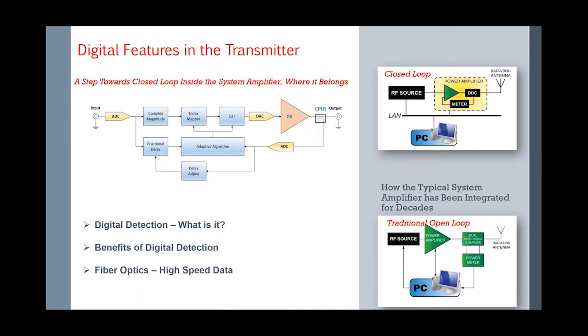The advantage of combining digital with RF is the capability to correct the errors existing in RF amplifiers. The idea is: let's put it in class AB, make it more efficient, and correct the errors digitally.